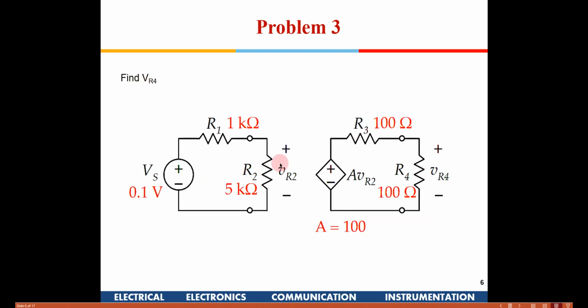Now this is actually an equivalent circuit of an amplifier. What an amplifier does is, when you apply an input signal, it will have a huge input impedance. This R2 is known as the input impedance of an amplifier, which will be huge, in the kilo ohms range. Whatever is the voltage across this input terminal will be amplified by a certain factor, which is known as the gain.